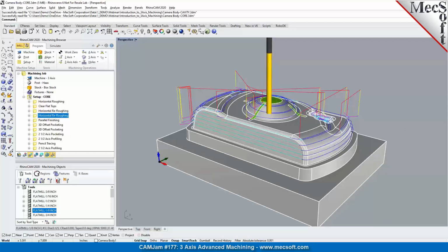So by nature, we are detecting bitangent contacts, and in some cases, these are more than two contacts. In some situations, except if you're cutting a fillet, for instance, with a cutter of the same radius, it is really a very difficult mathematical problem for us, because you're going to have very many places where the cutter is